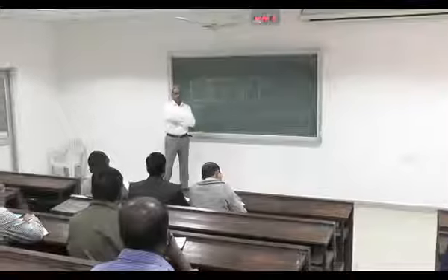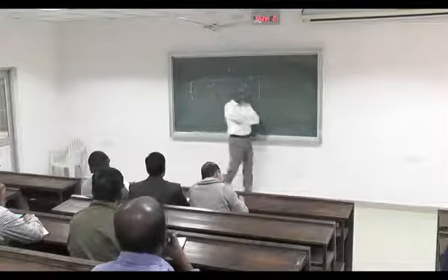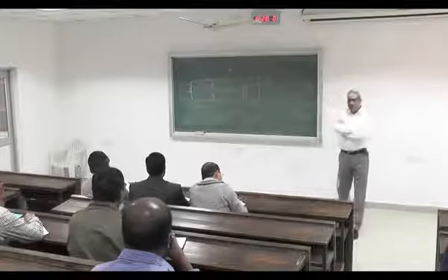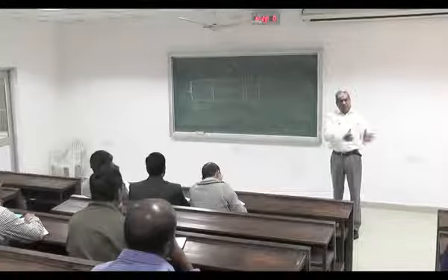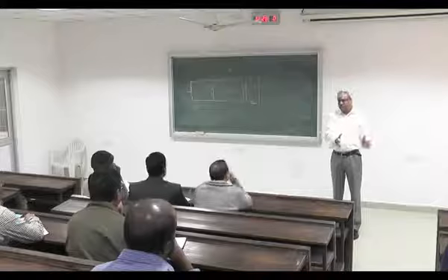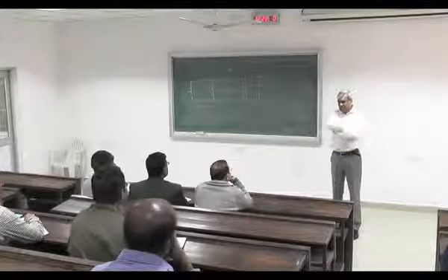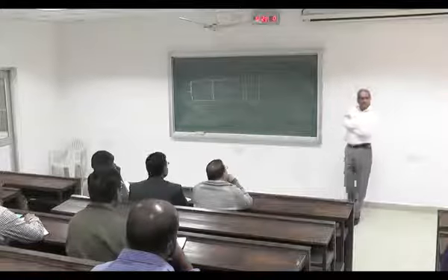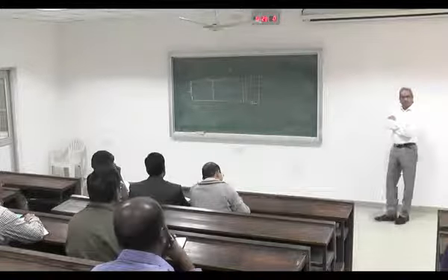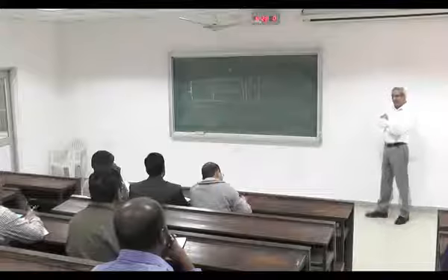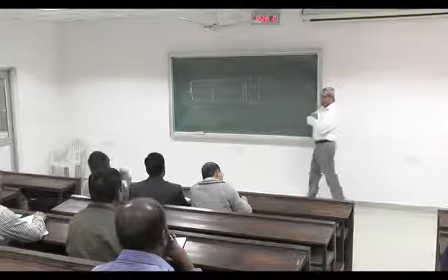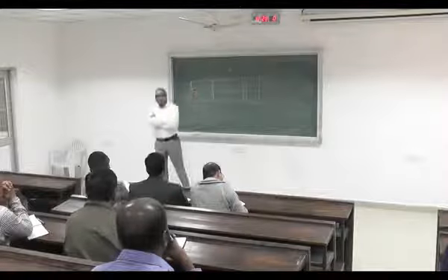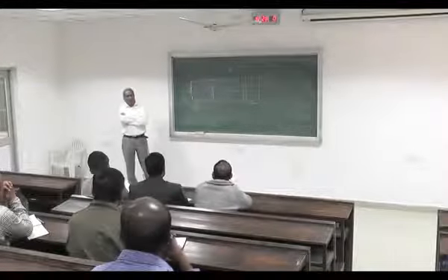And now, if you want to do pulse width modulation, PWM, then let's say you are going to 10% duty cycle. So now you have 10 nanoseconds for that pulse. And you have all the feedback. You're sensing voltage, you're sensing currents, and so on.